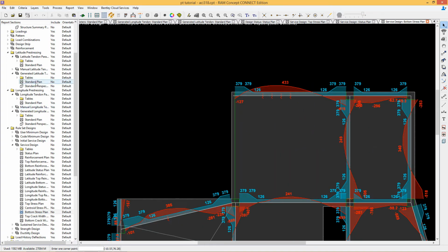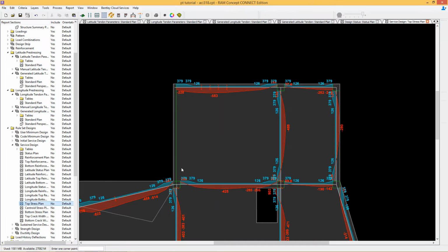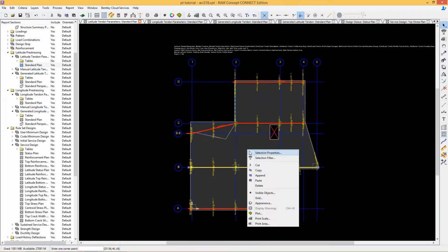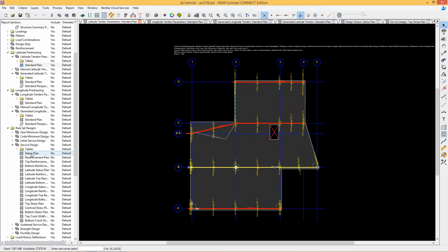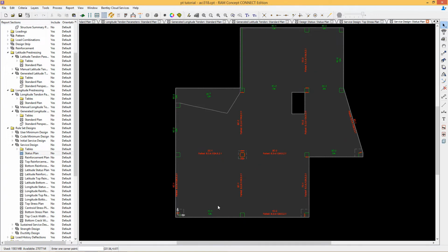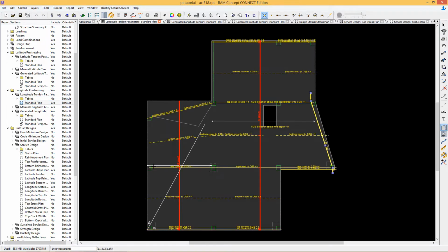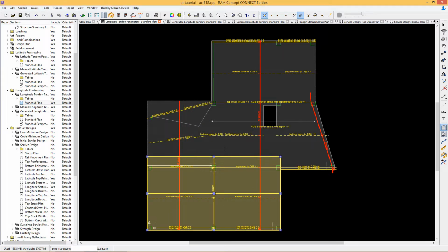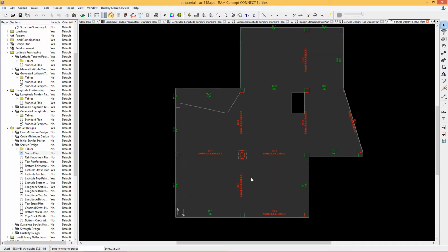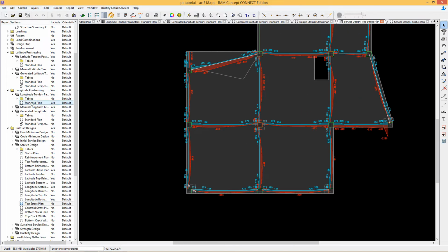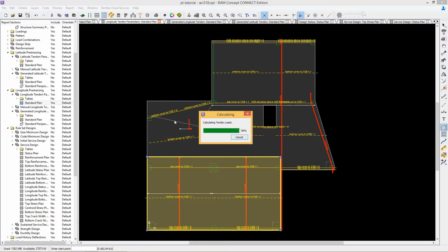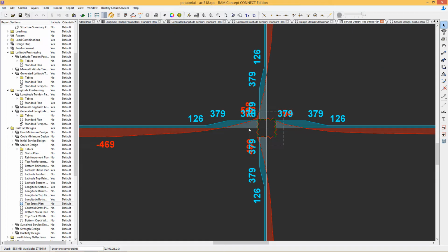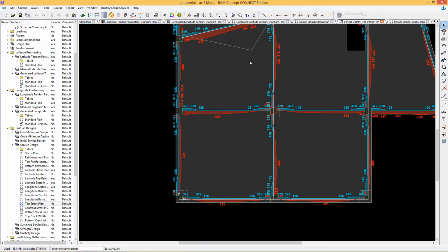Rather than going through this entire iterative process in real time, I'm going to speed up the video for the rest of the process, but we will go through the entire process from start to finish. And it really just requires continually changing, updating the tendon quantities, potentially profiles, running the model, and then evaluating the impacts on stresses. So I'm told by engineers that this process on typical size models can take 4 to 8 hours for a single design just to iterate to a single satisfactory solution.